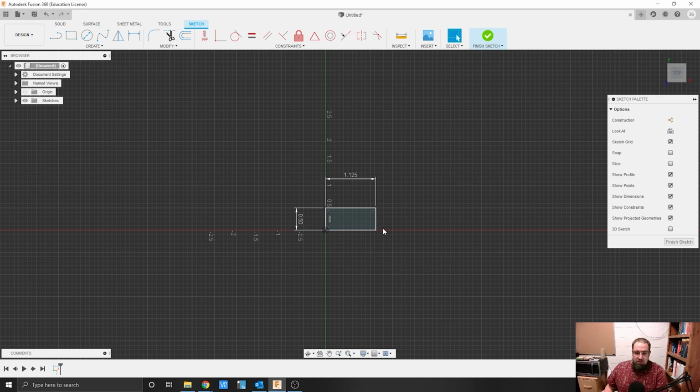Now you might question and go, well, why isn't this showing perpendicularity in between all of these other ones? Why is it not showing it here? It's actually showing it there without referencing it. If we were to utilize the constraints, it wouldn't work, because that would mean that it would be over constrained. But it's saying that because of the identifier with this point right here holding vertical to it, this also has to be vertical. And since this is perpendicular, this one also has to be perpendicular. So it doesn't need to show that, but we do know that that's confirmed.